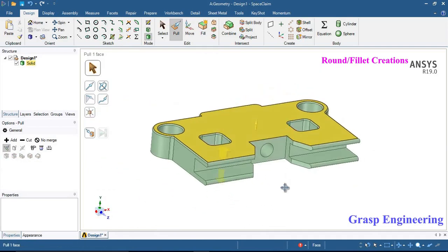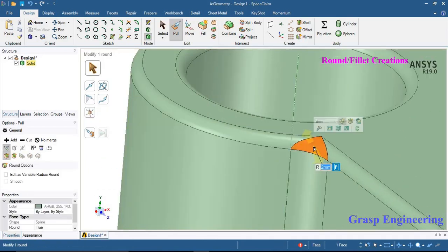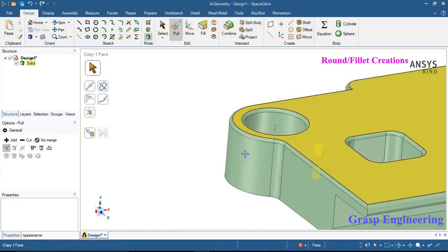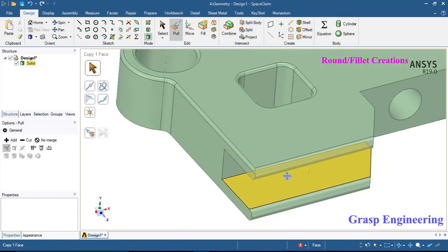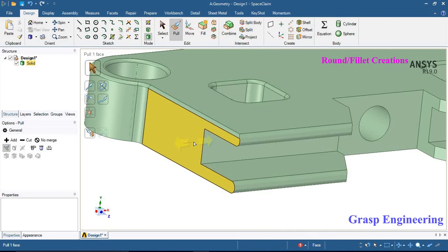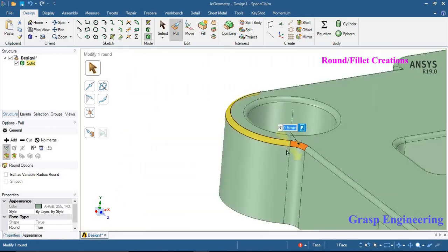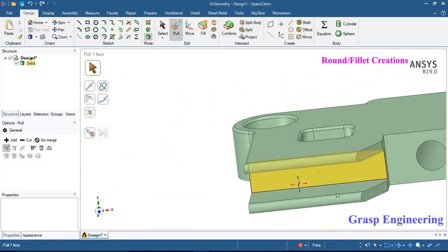Similarly, I will explain one more time. If you see here, click over here, and you have different features, like if you want a corner like this, or a corner like that, middle corner, or if you want sweep around corner, then you can click on that and it will automatically calculate. It is also useful for us to avoid meshing issues, because if the feature is like that, it will create a problem for the meshing. That's why this is very useful to create a proper mesh.